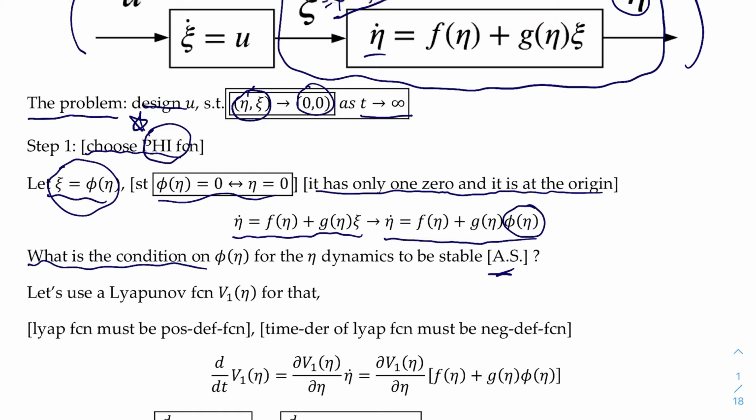Meaning let's construct a Lyapunov function, a typical quadratic form, and construct its time derivative, right? And let's determine under what condition this time derivative of our candidate Lyapunov function becomes negative for which input. The problem at that point becomes an algebraic problem, and it is something that we can handle, compared to the PDEs, partial differential equation type of problems, okay?